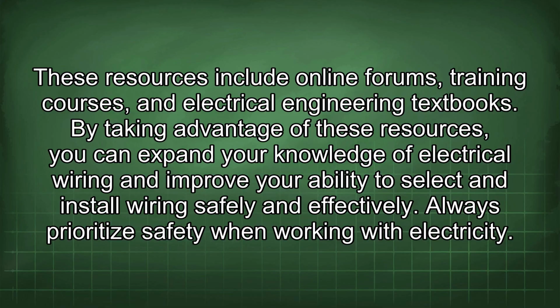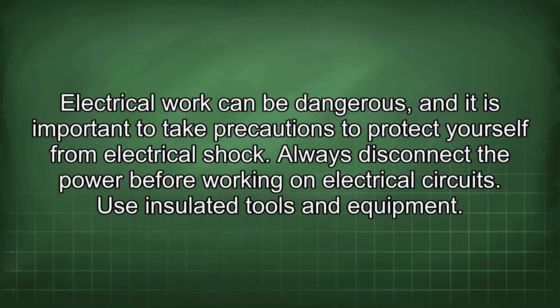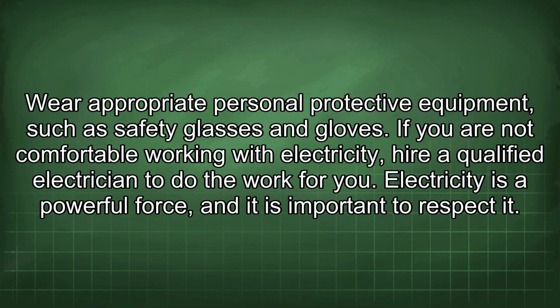Always prioritize safety when working with electricity. Electrical work can be dangerous, and it is important to take precautions to protect yourself from electrical shock. Always disconnect the power before working on electrical circuits. Use insulated tools and equipment. Wear appropriate personal protective equipment such as safety glasses and gloves. If you are not comfortable working with electricity, hire a qualified electrician to do the work for you.